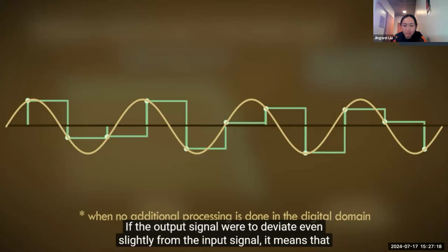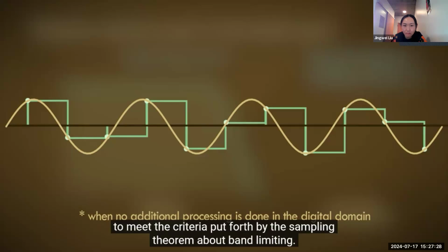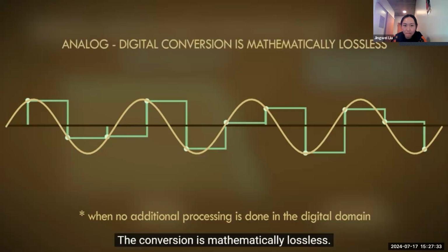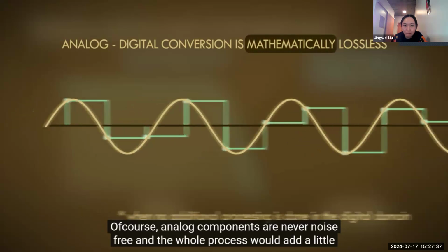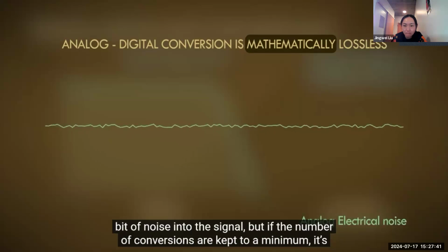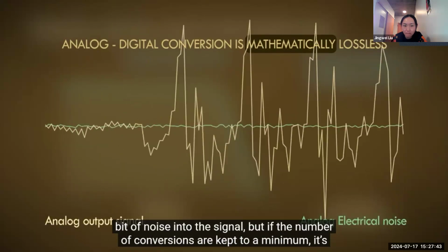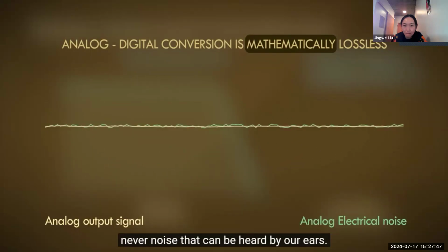If the output signal were to deviate even slightly from the input signal, it means that it would have to contain frequencies higher than the Nyquist frequency, and it would fail to meet the criteria put forth by the sampling theorem about band limiting. The conversion is mathematically lossless. Of course, analog components are never noise-free, and the whole process would add a little bit of noise into the signal, but if the conversions are kept to a minimum, it's never noise that can be heard by our ears.